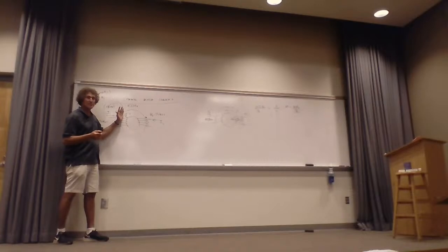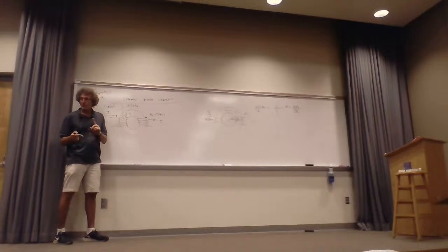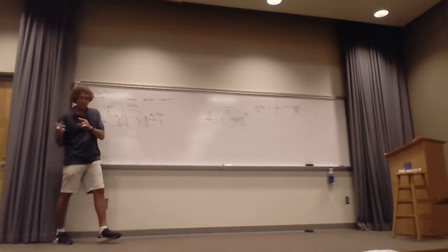Some of this stuff, even though it's a small amount, is spurious and comes out, so you don't get perfect flux linkage. That's one of the reasons. Other things are imperfections in the coil and wire, and there may be an asymmetry, so you just have to appreciate that fact. But generally speaking, they're about the same. Maybe not exactly, but real close, and that's what you want.